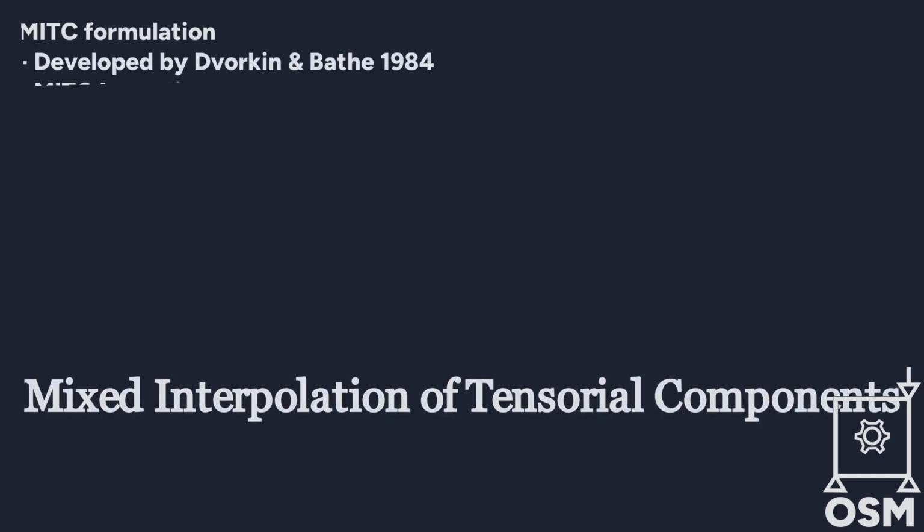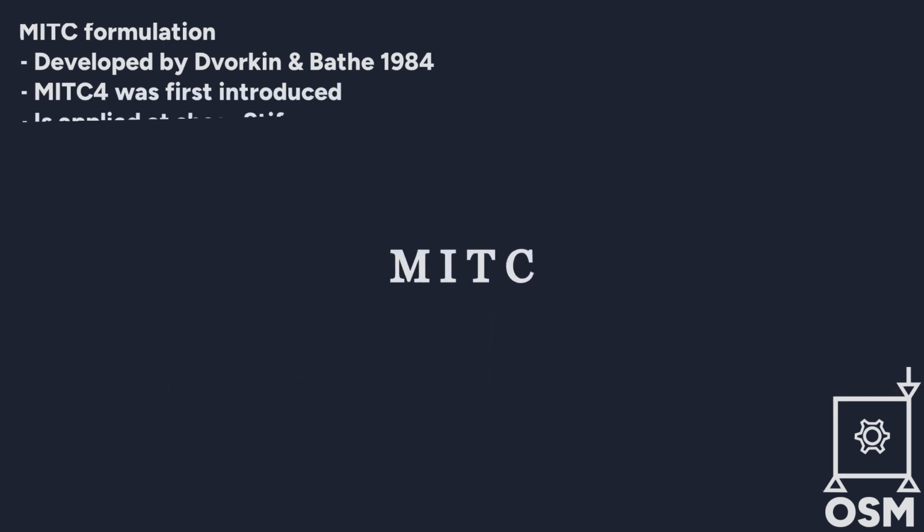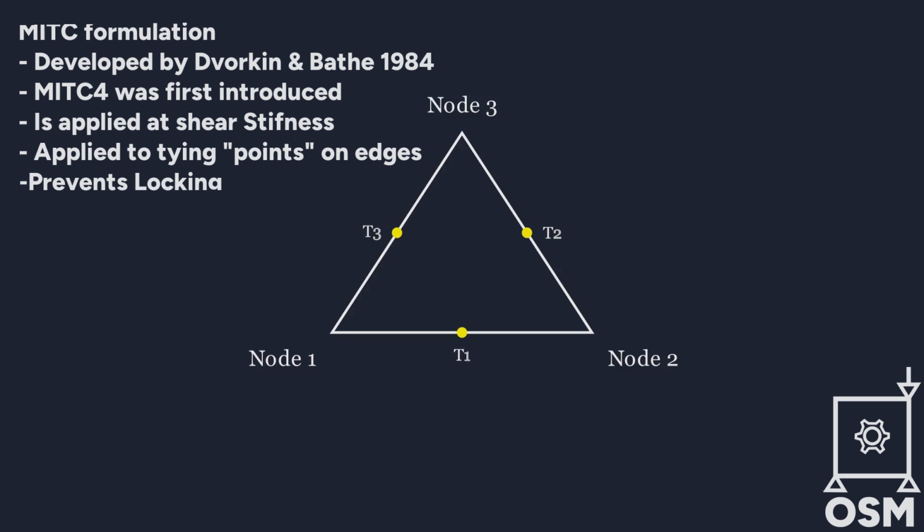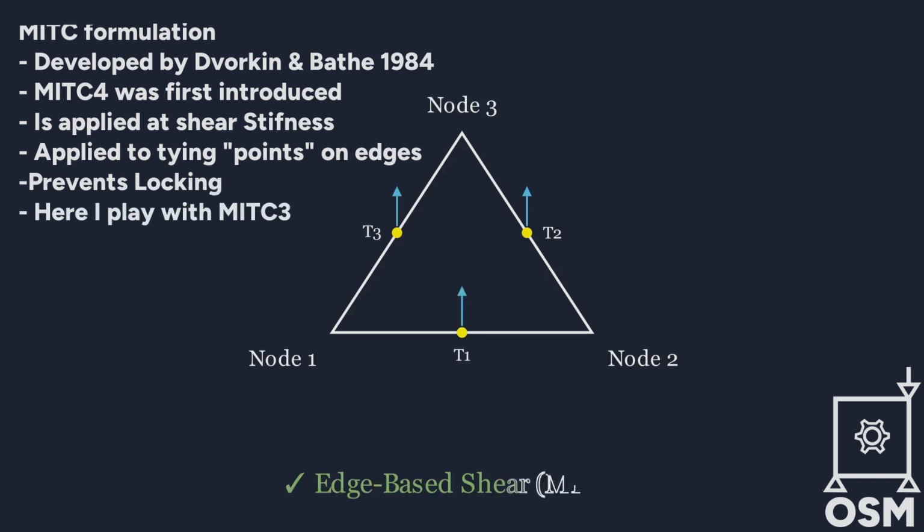MITC stands for Mixed Interpolation of Tensorial Components. It's a technique to fix how transverse shear strains are computed. Instead of using node values, we tie them to points along the edges.